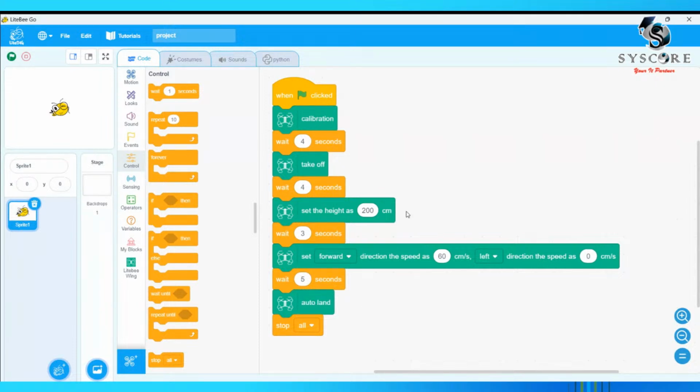Okay, and then I would like to teach another coding. Not another coding, like a safety emergency coding. What is a safety emergency coding? In case you are controlling your drone as a pilot, you can take it off. But in case it collides or crashes into an obstacle or onto people, you need to emergency stop your drone, right?